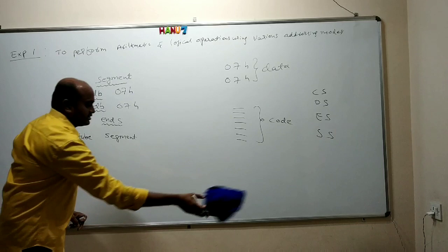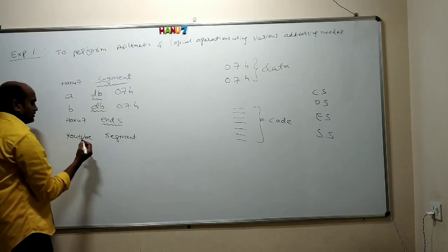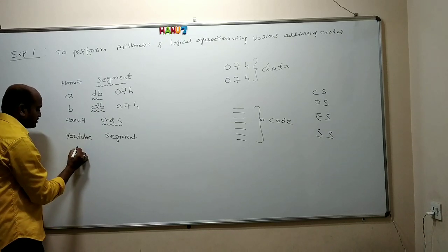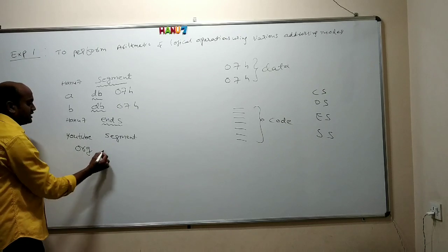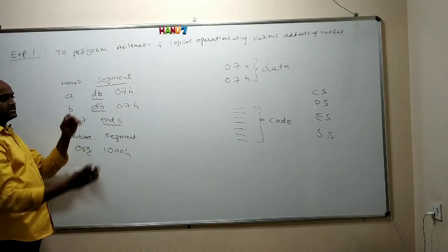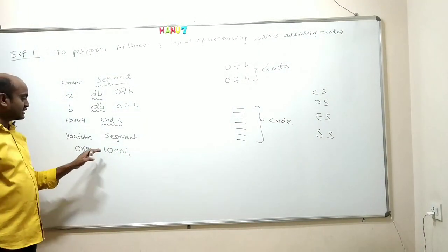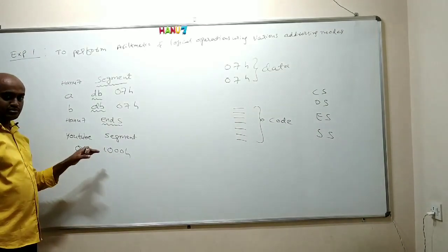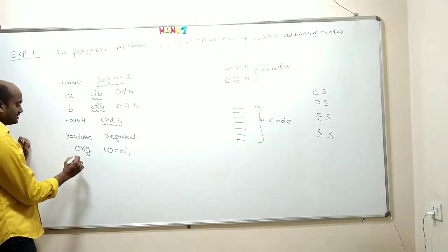So I want to write U2 segment. As soon as I start this segment, I have indicated that my code is starting from 1000 memory. Inside the code segment there are 64K locations. You have to clearly tell in which location your code is going to start. So I am indicating that code starts from 1000 memory. This is also a keyword.